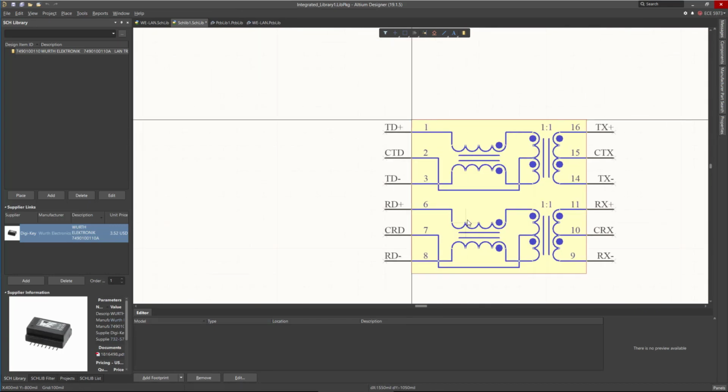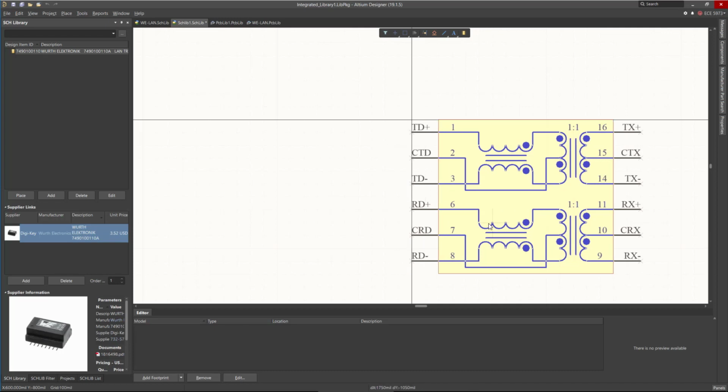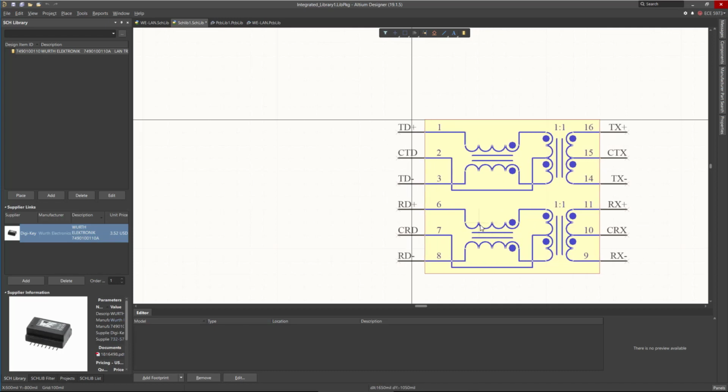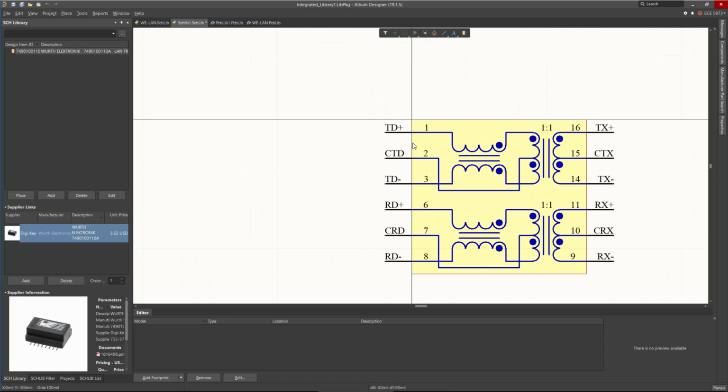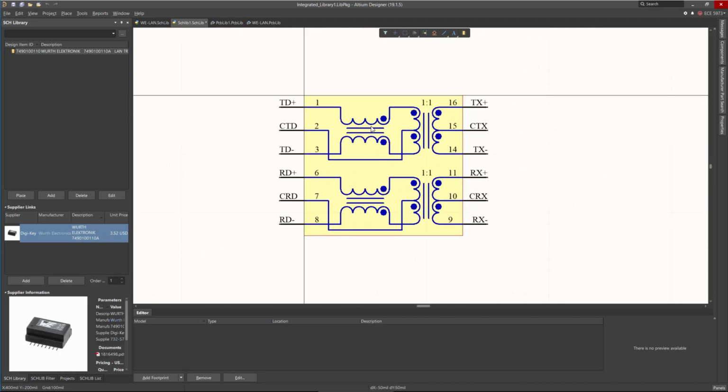My recommendation for placement, in order to be consistent, try to place the edge of the component in this corner in here. Now this will guarantee consistency. For all the components, when you move them around and copy them or create them, make the top left side of the component be at this 0, 0 reference point. So now this is the schematic.